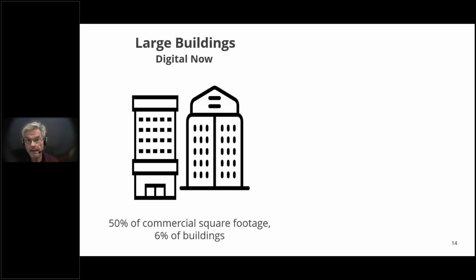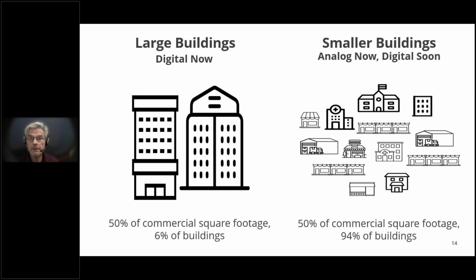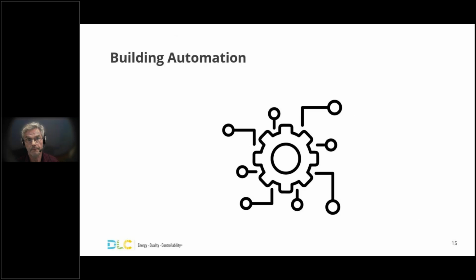Occupied standby mode is also feasible in some smaller buildings, usually with old-fashioned analog dry contact technology. But thermostats are being introduced now with wireless Wi-Fi and even Bluetooth connections to support plug-and-play digital versions of occupied standby mode in smaller commercial buildings without full-blown building automation systems.